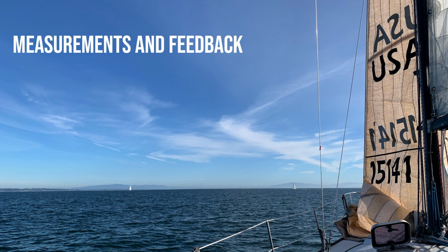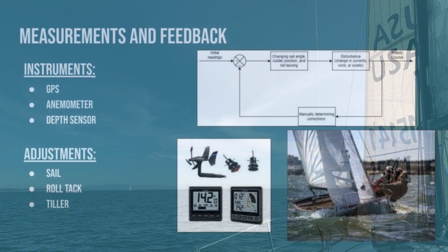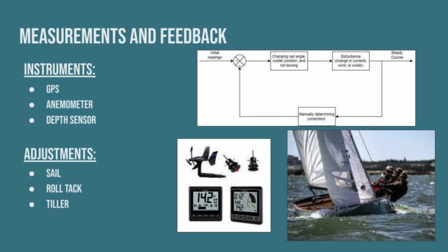The sailboat system uses instrument and visual inputs paired with manual maneuvers. While most small sailboats do not contain sophisticated navigation equipment, GPS and anemometers are regularly used on bigger yachts. GPS receivers on sailboats rely on satellite signals to determine the boat's precise location and velocity. These calculations are established within the Earth-centered Earth-fixed reference frame, providing a stable coordinate system with the Earth center as the origin.